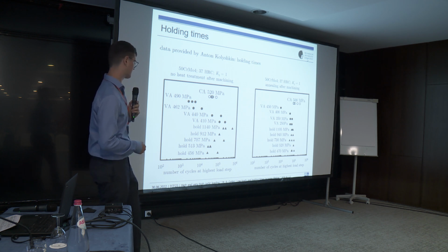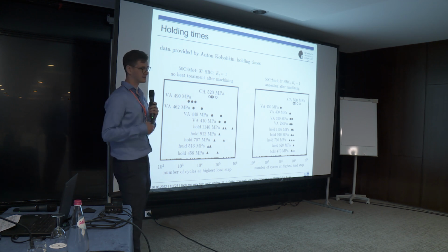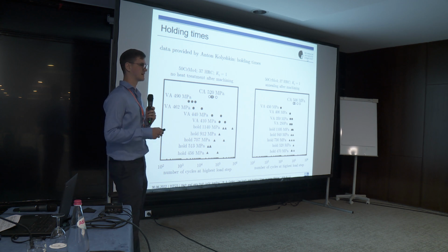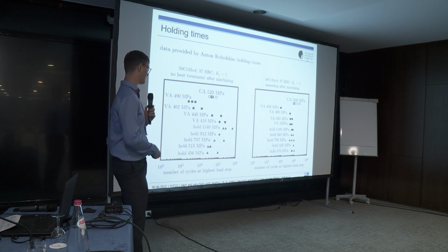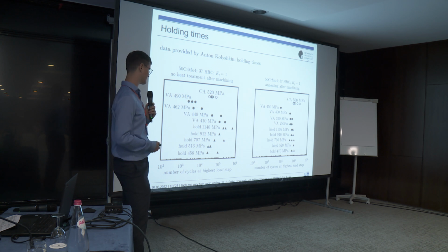Then he did other experiments which are even more interesting because he added holding times. That means he did a constant amplitude test, and after a number of cycles, he stopped the constant amplitude test, held the specimen for a while at different loads, and then after that resumed the constant amplitude tests.